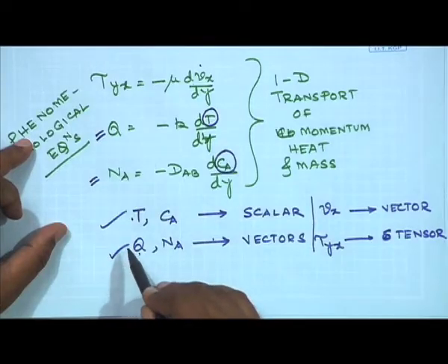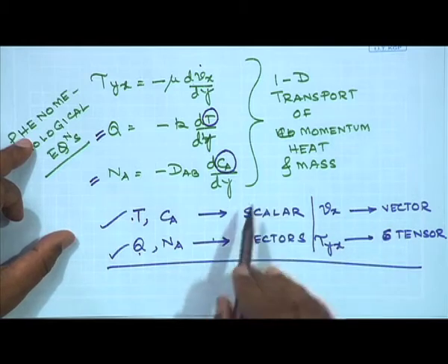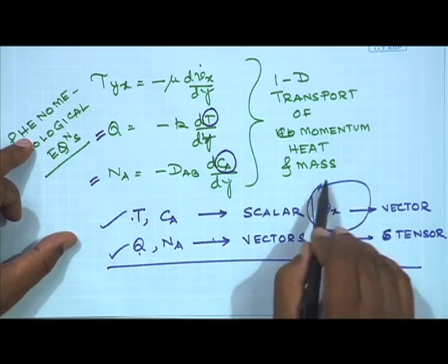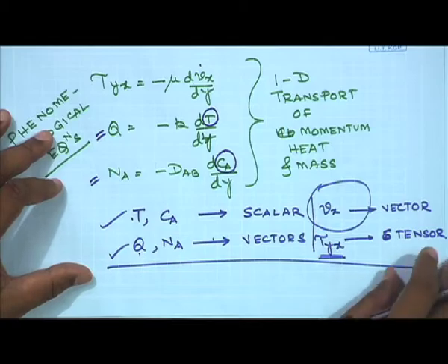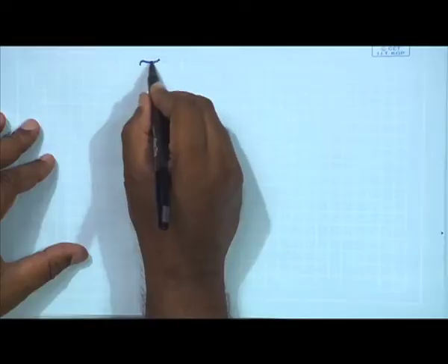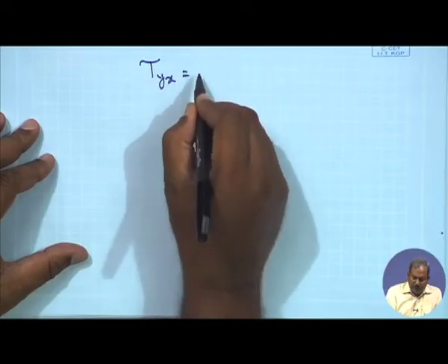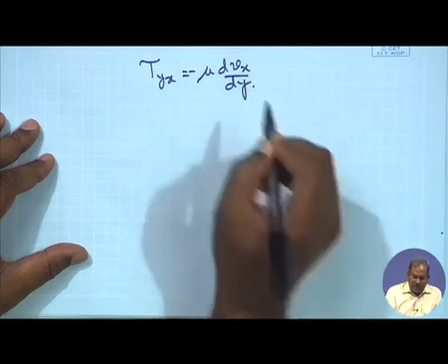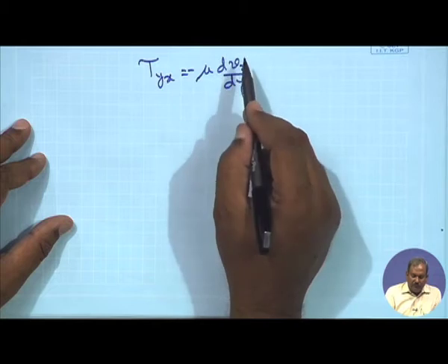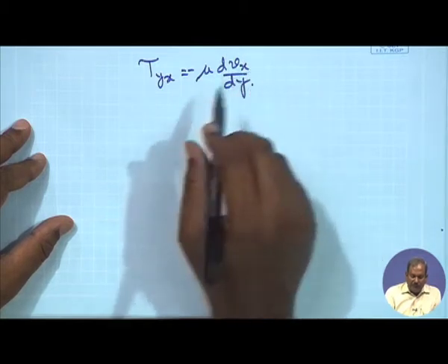So we should keep this in mind, as the complexity due to the vector nature of the velocity, and therefore the 9 possible components of tau, will come back. We will explore it further in our subsequent lectures. But in the first part, I am going to be concerned with the initial one, the Newton's law of viscosity and the use of Newton's law of viscosity under different conditions.